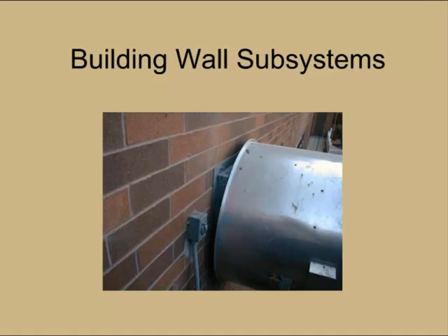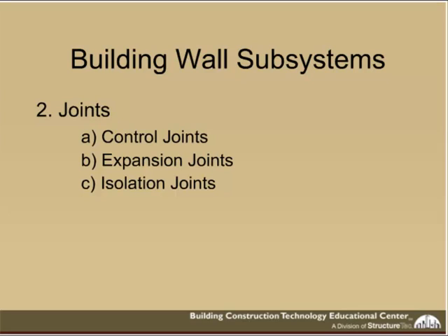If these things aren't sealed properly, that sealant is failing or it's open, that's a direct avenue for moisture ingress into the facility. So you just want to make sure that if you have penetrations through the wall system, you are making sure they're sealed properly and continuing the maintenance, because if not, it's just a direct avenue for moisture into the system.